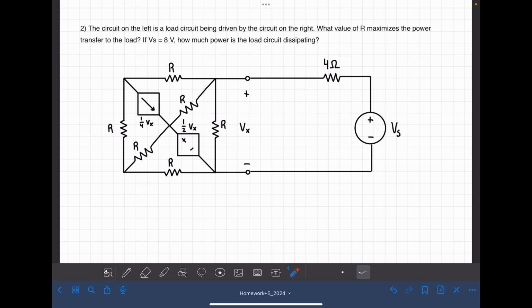So we have some dependent sources in this thing, but no independent sources. So the best method to do this would be the external source method. I'm going to use a voltage source because that'll clear up some of these variables here. Set it to 1 volt, and remember, we cut off our source when we're just finding the Thevenin resistance of our load.